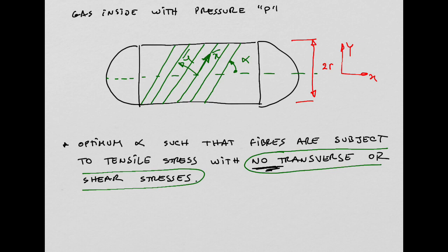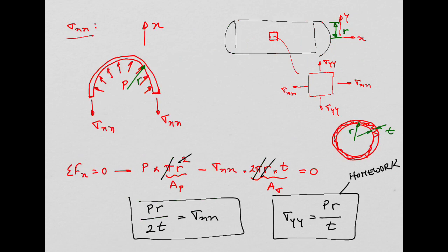When you put the pressure in the pressure vessel, this angle of 30 will mean you will have some loading in the transverse direction to the fibers. And most probably it will fail, eventually. We are going to see a failure after the break, when we talk about the failure criteria, how we are going to assess that.